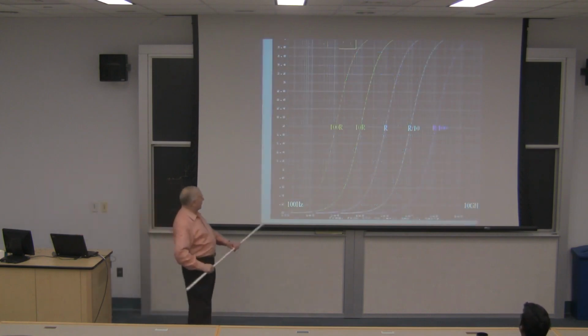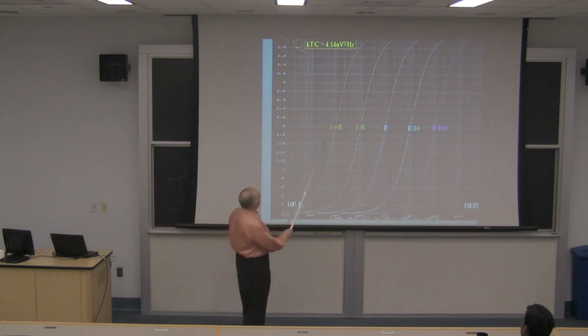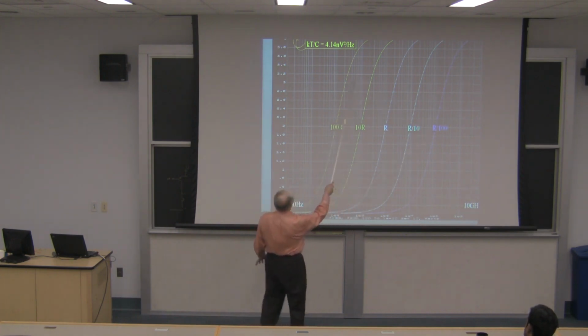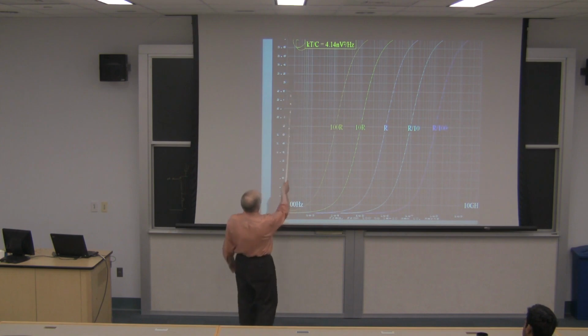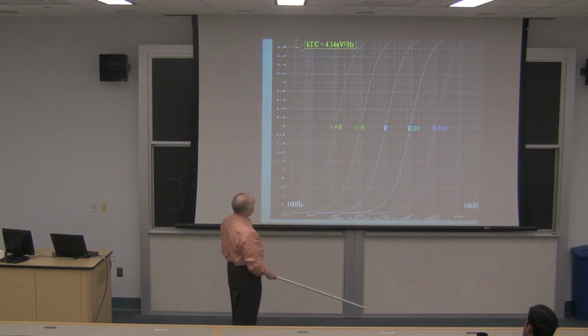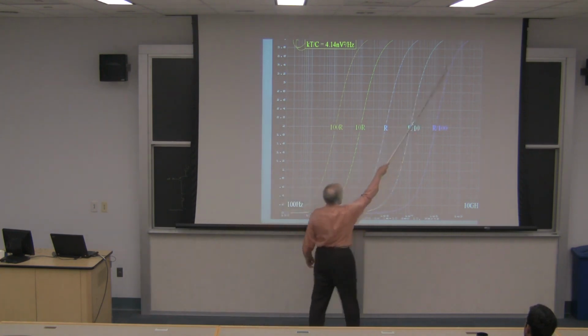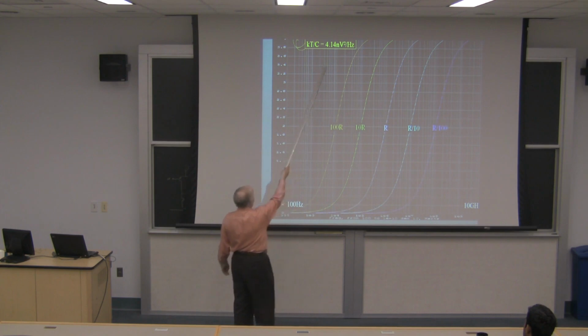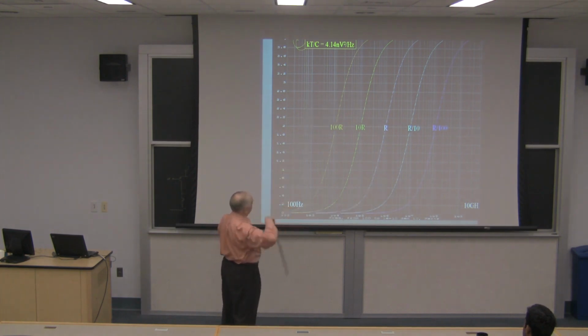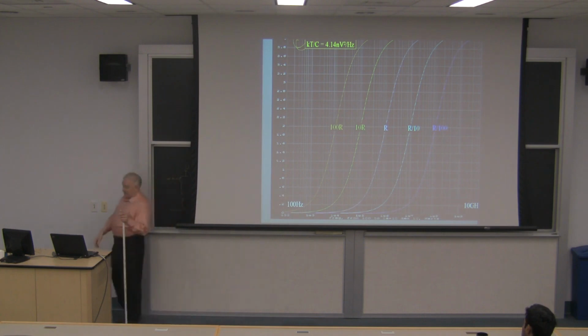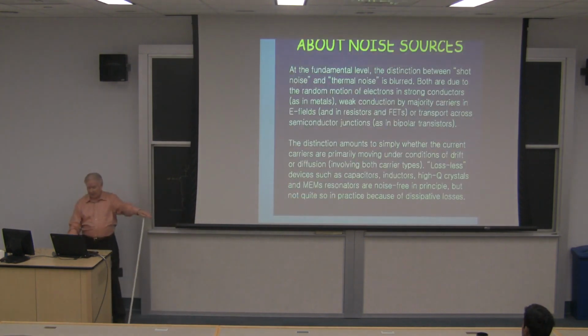It's not very interesting, but I just changed the resistor from R to 100R or a 100th of R, and again my picture's unfortunately a little bit cut off here, but they all end up at kT/C of 4.1 microvolts for 1 picofarad, which we rehearsed. So it seems like the asymptote in terms of the voltage noise spectral density is related directly to the capacitor, but it's really just a consequence of that integration over time. That probably doesn't make a lot of sense, but anyway.